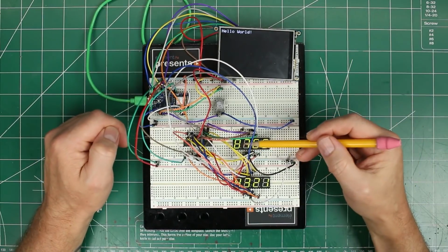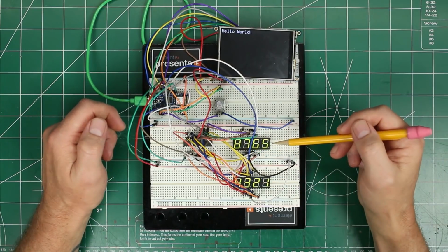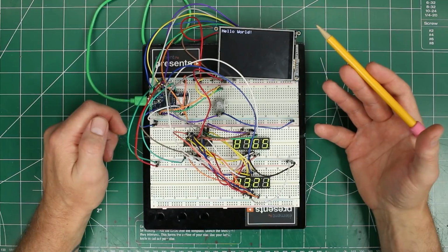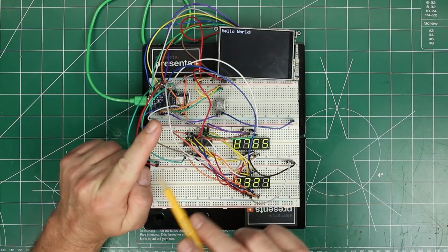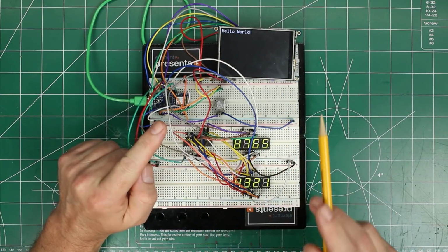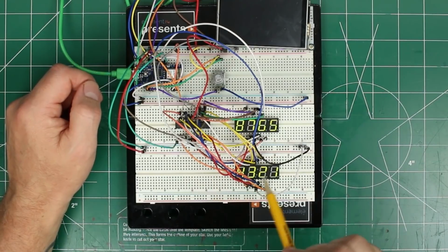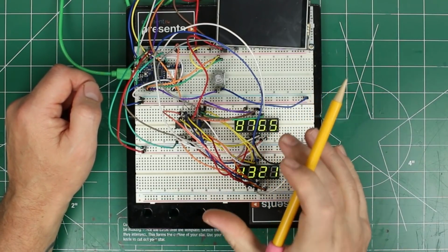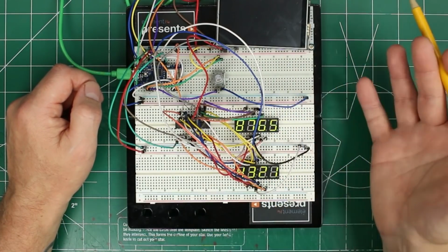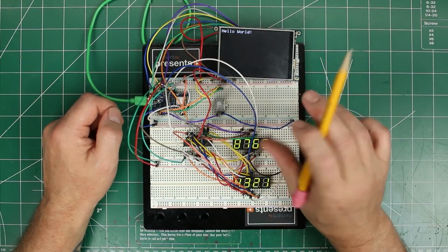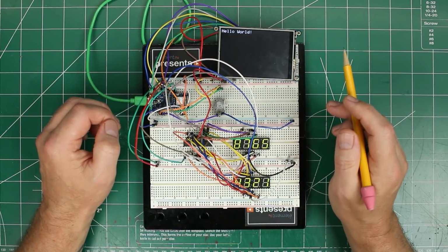The only weird thing is you can see this is digit 0, 1, 2, 3, 4, 5, 6, and 7. It's reversed from what I have in the software. I think the function is called print digits or write digits, something like that, and it takes 8 digits, and in the software I have 1, 2, 3, 4, 5, 6, 7, 8. For whatever reason, it's backwards here. And I'm not going to change the pins. I could just swap them all around so it's right, but I want to keep the pins correct so the schematics are right, and it's less complicated when I build the perf board. I'll have to do some kind of weird stuff in software where I flip the whole thing around so it prints out right, but that's just software, not a problem.